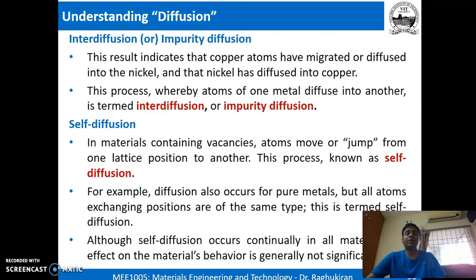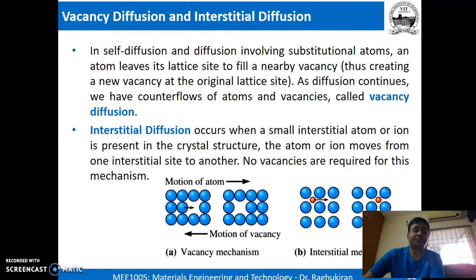You might have, for example, some vacancy at some place, like we already know what a vacancy is, right? It is a point defect. So another adjacent atom might come and occupy this particular vacancy, right? That is always on cards. That is what we call, whatever type of diffusion happening within the material, not from one material to the other, self diffusion.